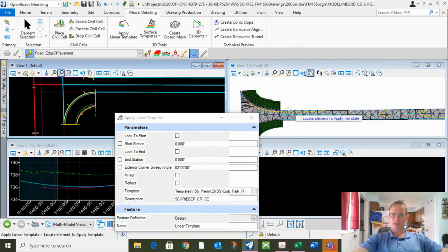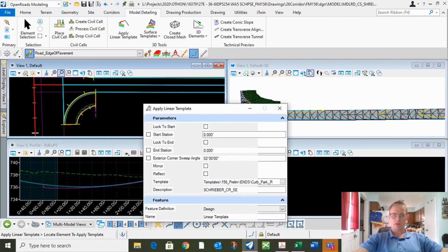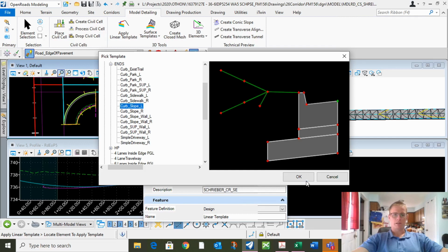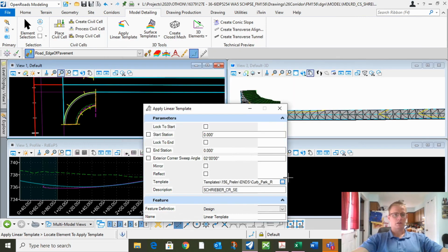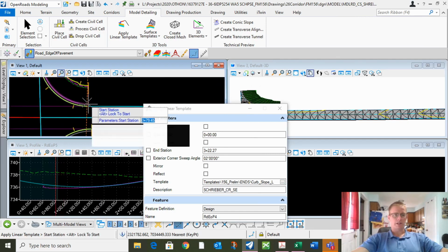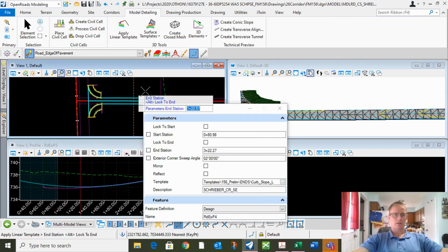So now we need to create the curb going along the rest of the cross street. And so just create curb, 2-foot buffer, and then tie in. This is going to be the left side. We'll start here. Go to the end.